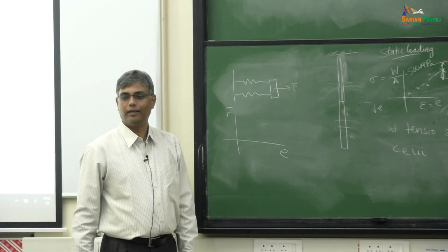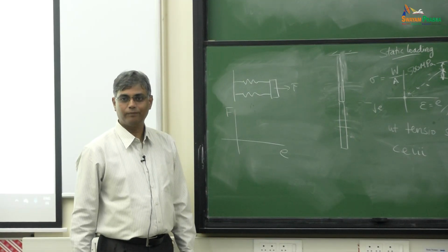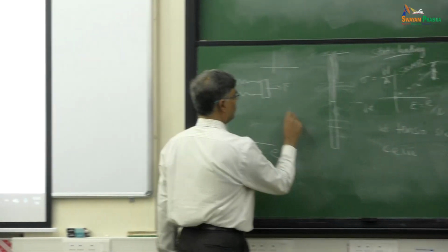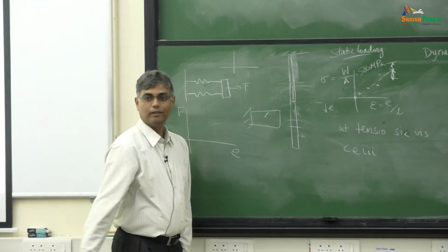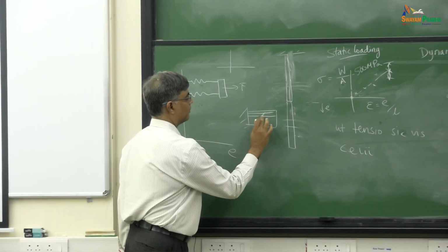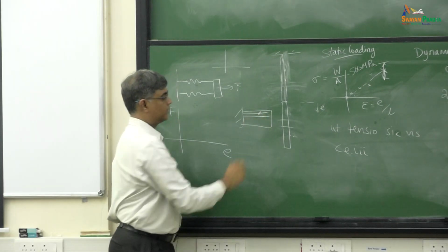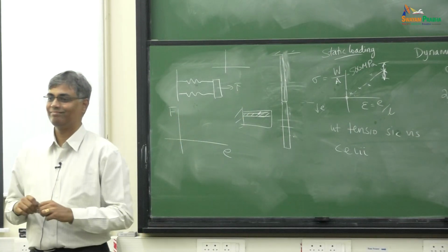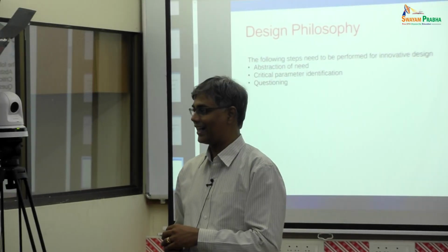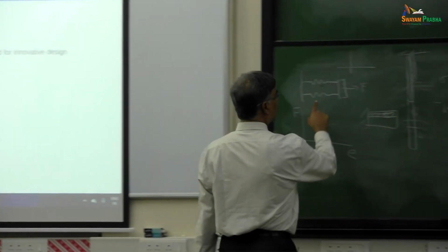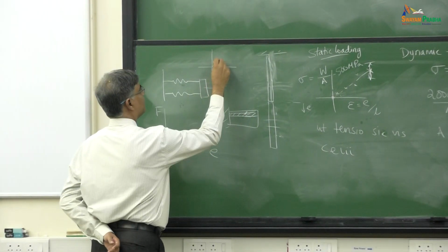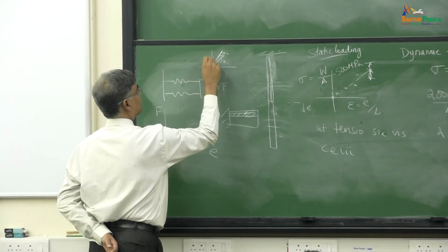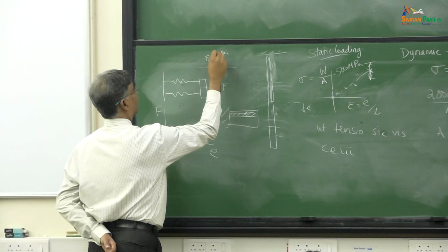For this two spring model, this spring is one which has a crack in it. You remember I said there's a crack here. So this entire region I'm modeling as one spring. So the spring is a bit weaker than the spring where there's no crack. So I'm going to model this entire bar as just two springs, but each of these springs will have slightly different K1, K2 and failure strength, failure load F1 and failure load F2.